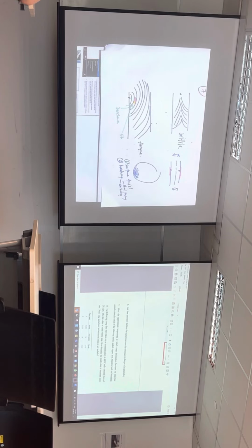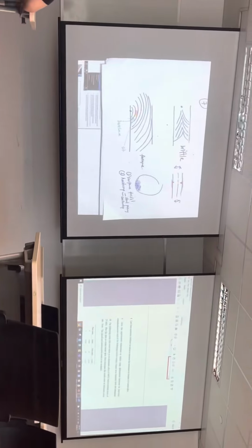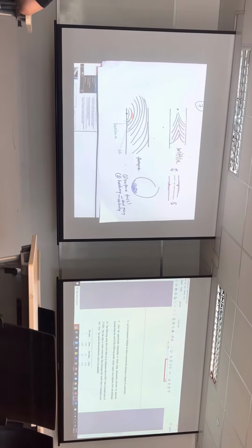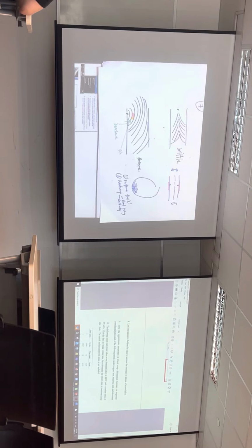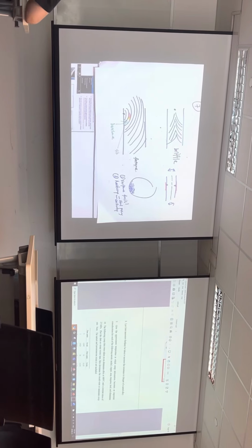Carburizing means you put the landing gear inside a carbon-rich environment and force diffusion to cause a higher carbon concentration outside than inside. Higher carbon concentration is always harder, so it also protects the part from fatigue failure.